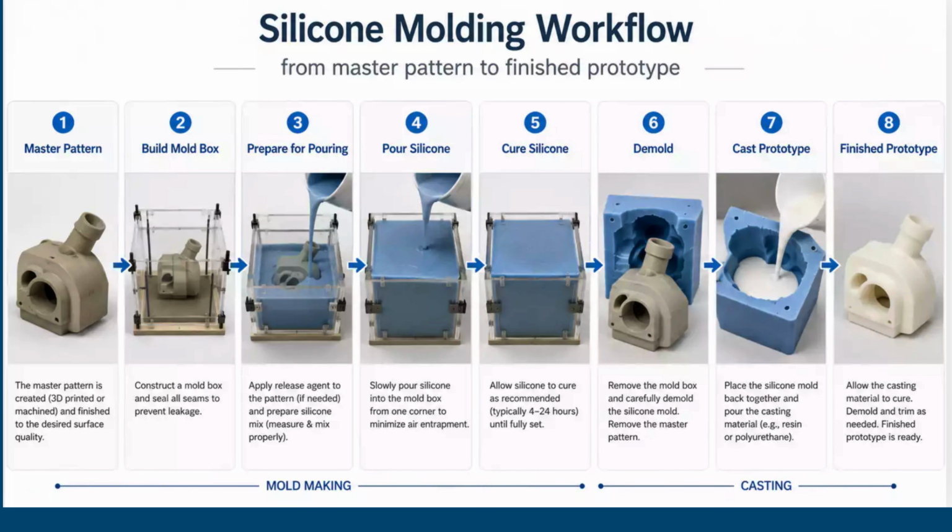Its success is rooted in the unique chemistry of PDMS-based elastomers, whose flexible siloxane backbone provides outstanding thermal stability, elasticity, and dimensional fidelity. Modern molding techniques, including vacuum casting, pressure casting, rotational casting, and LSR injection molding, offer complementary advantages depending on production volume, material selection, and performance requirements.